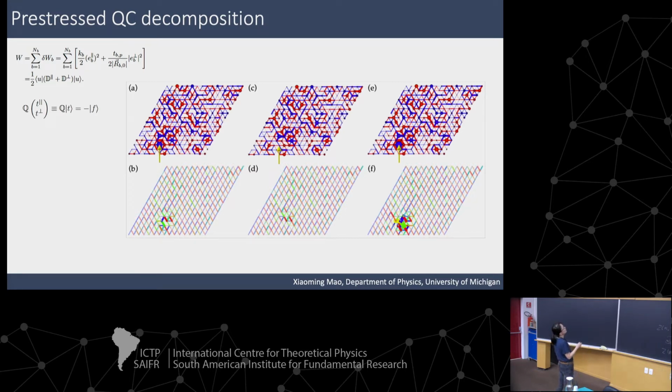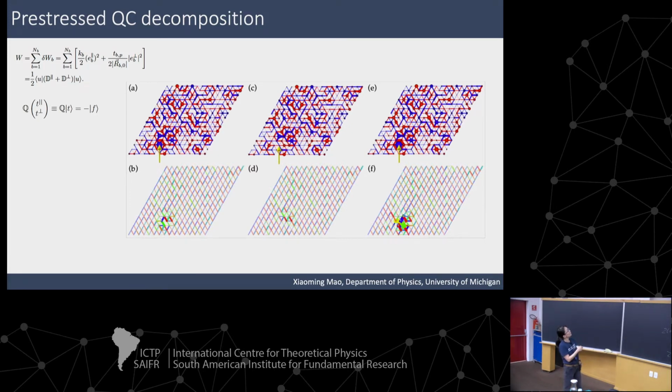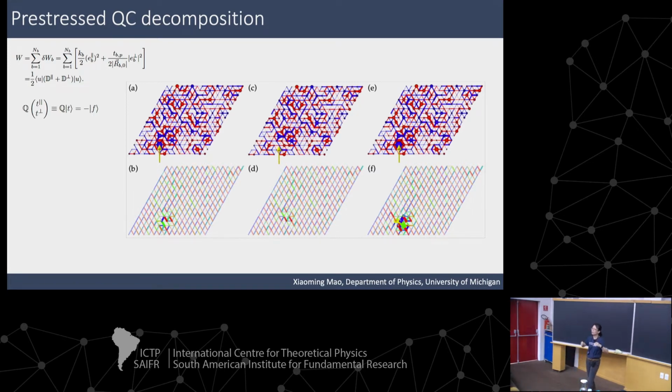And basically, you can write the elastic energy as a part of the central force stretching of the bonds, and add another term that comes from the fact that the bond carries tension or compression already. In fact, this coefficient can be either positive or negative, because when it carries compression, it wants to become unstable, right? It wants to have transverse motion. So you could have a negative coefficient here.